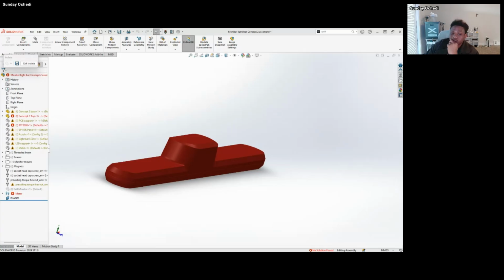Okay, so two important questions. When you consider manufacturing, it depends on whether the product is supposed to be manufactured and what manufacturing method you're planning to use. In my case, I'm planning to use a 3D printer, so whatever tolerancing I'm considering, I ought to consider how my 3D printer prints.